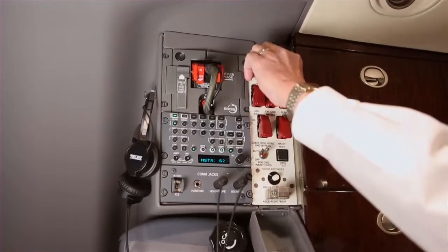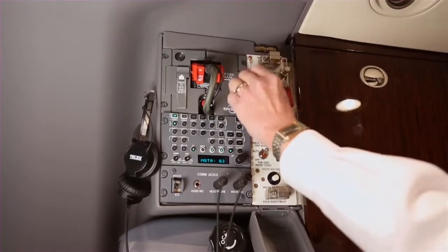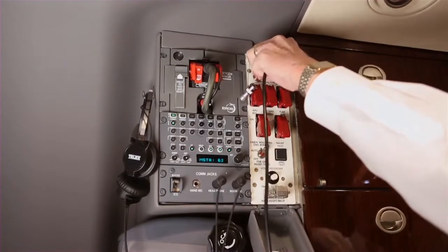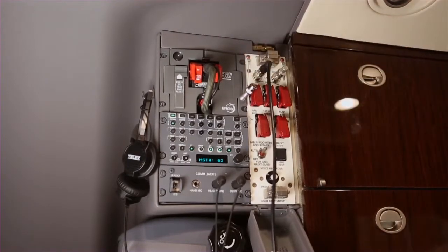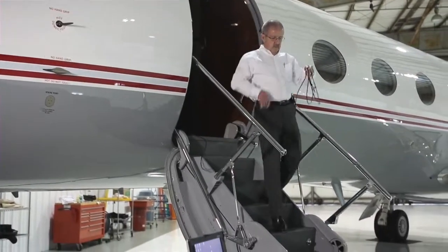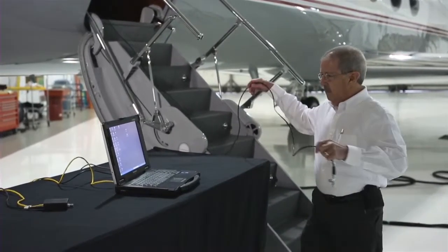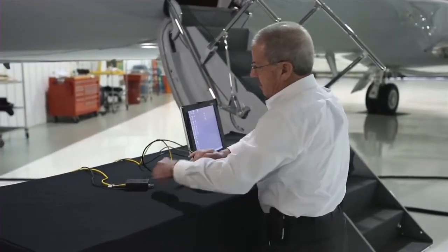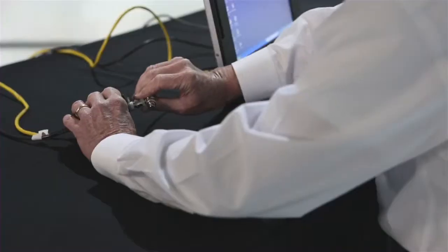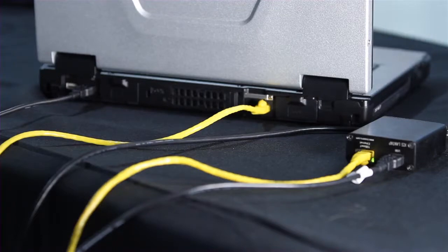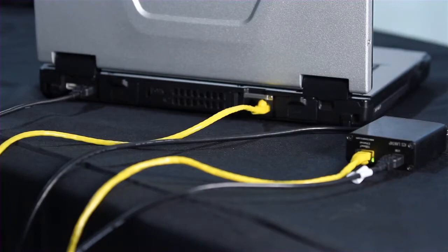Once the aircraft is set up for the load, connect the remote terminal to the aircraft LAN. On the Gulfstream G450 and 550 aircraft, there are 2 LAN connections in a panel behind the co-pilot seat. Using the coax cable from the LANTAP 10 kit, connect one end to the LAN. Connect the other end to the BNC connector on the LANTAP. Connect one end of the Ethernet cable and USB cable to the LANTAP and the other end to the remote terminal. Now we're ready for the load.